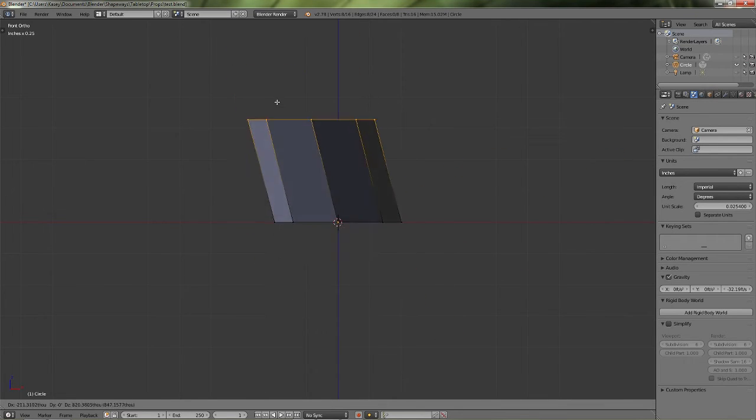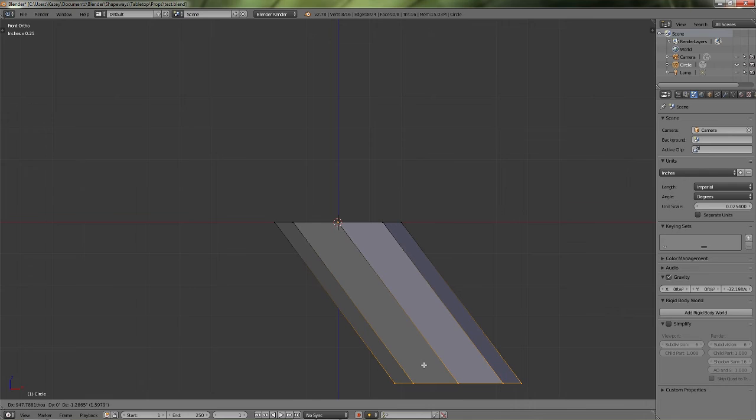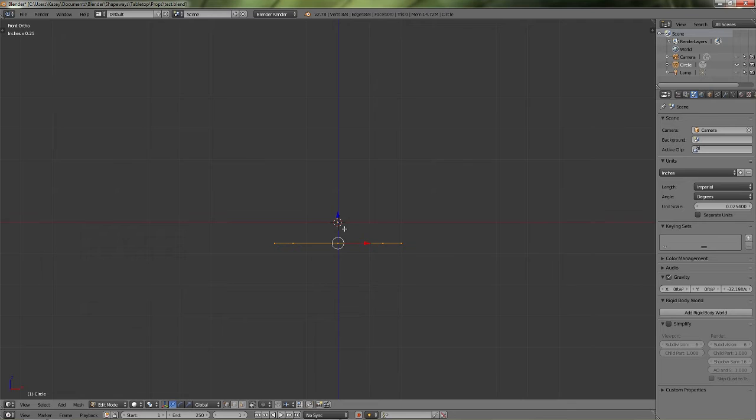Awesome. Now I have this thing attached to my mouse pretty much. So you can either take it and click to wherever you want it to be, or if you hit escape after you extrude it and grab your arrows, you can move it to wherever you want. It's usually my preferred method because usually I'm not going in a weird direction. Sometimes I am, depending on what I'm modeling. But for a vase, I want to go straight down. So I'll use that Z-axis arrow and pull straight down.